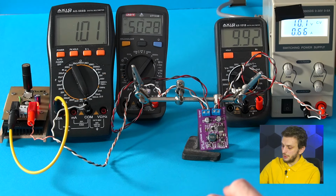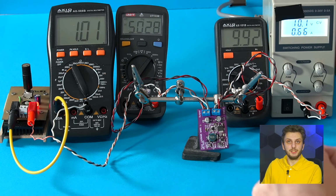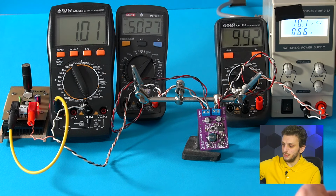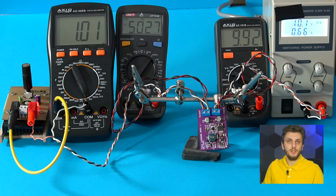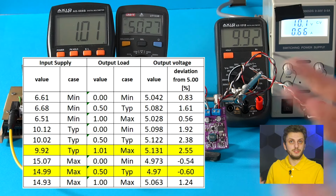And finally, this measurement needs to be carried out in all extreme case combinations, so maximum and minimum input supply, maximum and minimum load, maximum and minimum temperature, and usually a typical use case. And as an example, using this setup for this particular board, I got this set of results.